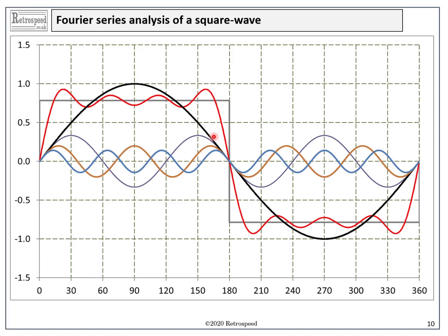And I should mention here the vital importance of using Fourier's series and not the FFT. The waveforms are periodic, and although there are special cases where the discrete Fourier transform can be identified with some of the coefficients, the FFT is the wrong tool for this work, and we should always use the Fourier series. Otherwise we'll run the risk of departing from the classical theory and coming up with the wrong winding factors.